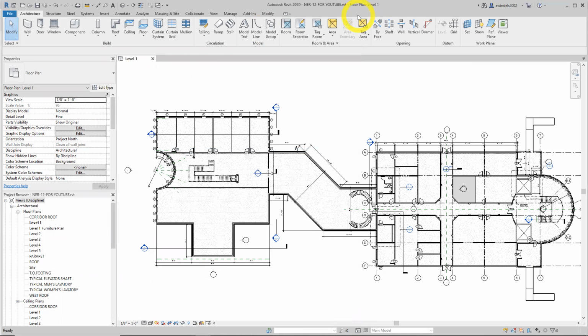Moving on to creating a dependent view. You create a dependent view very much the same way you duplicate a view, what we just did. Essentially, the function of a dependent view is to nest within a duplicate view of the host or parent view which you're duplicating. And then this nested view remains dependent on the host or parent in terms of how it's viewed graphically. That's the key. How it's viewed graphically is really the key.